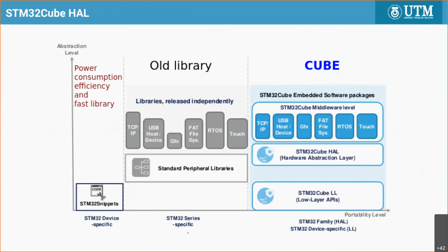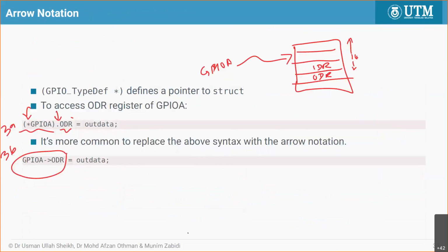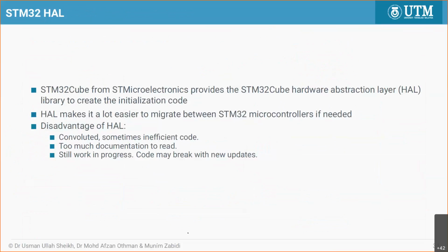And then you can also use method number 4 using the HAL. You want to access the GPIO, now you take advantage of the hardware abstraction layer from STM32. And the HAL only exists for ST Micro. Don't try to use this technique on other companies' products.